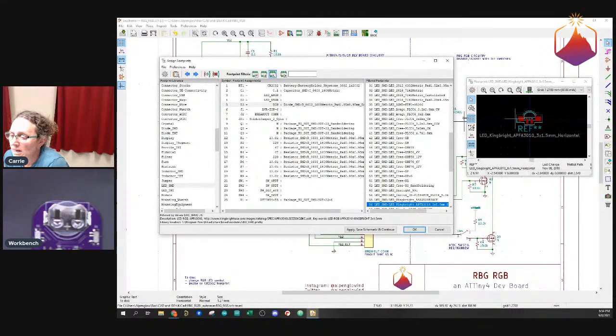So when you go from schematic to PCB and you assign all of your footprints, and I know we're getting late and we're not actually going to get to the fun part of connecting the dots in the PCB this time. Stay tuned for next week, folks. But the first thing you want to do, before you even place your components on a circuit board, is do that import so that you see all of the footprints for all of your components, and print that out 1-to-1 on your printer.